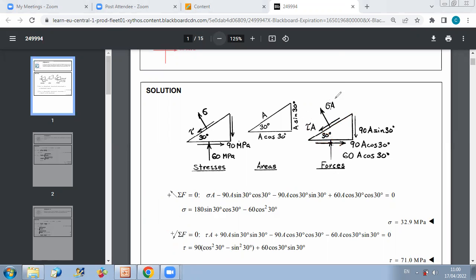The advantage of projecting on x prime, y prime is the following. Because you know that the shear is down, you can take the axis x prime like this here, and the axis y prime like this. Since you want just to determine the values, and since you are not using a formula, you can use any direction you want.